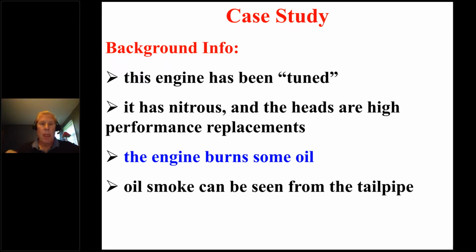It's high performance. And the tech, when I first talked to them on the phone, tells me a little bit about it, and I confirm this when I get there, and you'll see in blue here, there's the great clue: this engine burns oil. This engine burns so much oil that when it runs, I see blue smoke out the tailpipe, which is something you don't see on modern day engines much anymore. So this thing burns some oil. So keep that in the back of your mind as we progress.